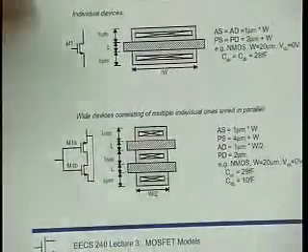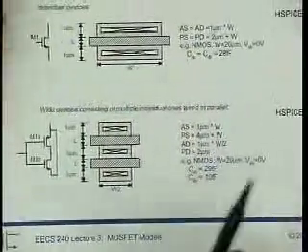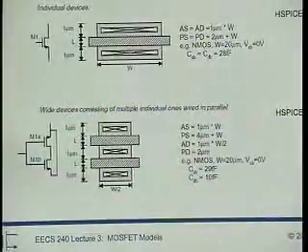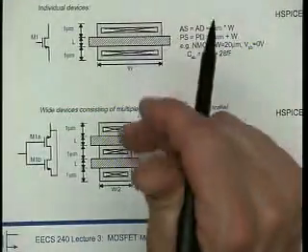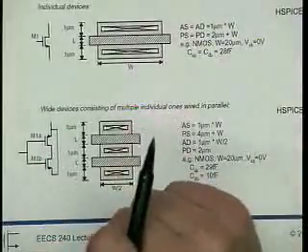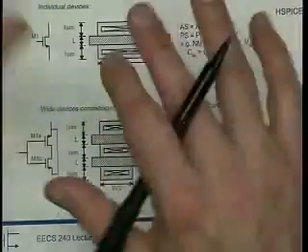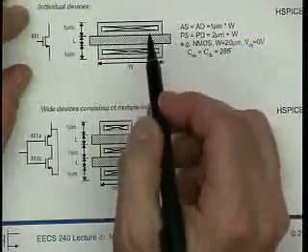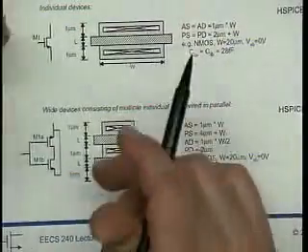Okay. One important thing is layout. Depending on how we lay out our devices, we get, in addition to the so-called intrinsic capacitance of devices, the CGS, also the extrinsic capacitance, that's the capacitance associated with the isolation diodes, source to bulk and drain to bulk and so on.